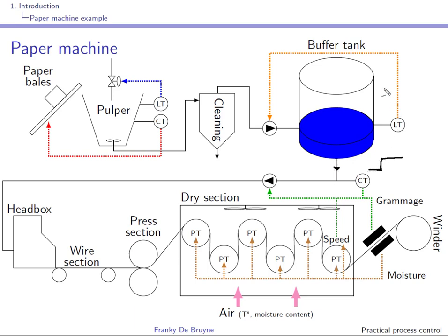Now imagine that you have a controller implemented here that is of the type implemented over here, a controller that will maintain the level in the tank very strictly. Well, this step-like demand at the output will propagate to a step-like demand at the input.